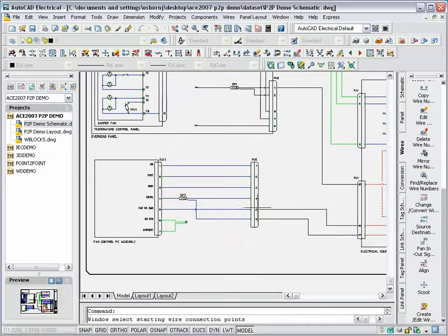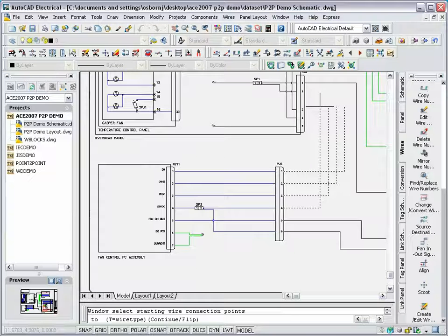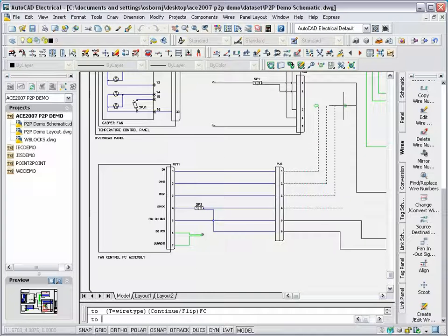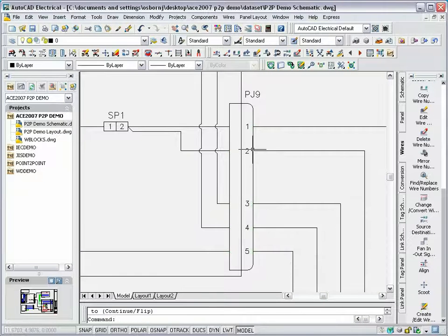Instead of inserting single wires repeatedly, you can create a multiple wire bus with a single command. After selecting the connecting pin and basic path, the wires will automatically land on the termination pins. Watch how the wire spacing automatically updates to the spacing of the connector pins.